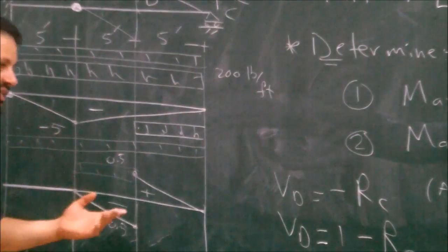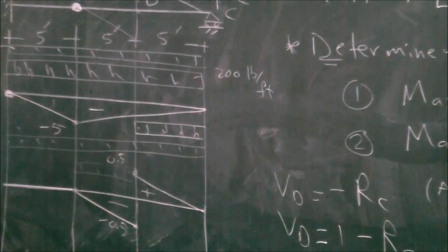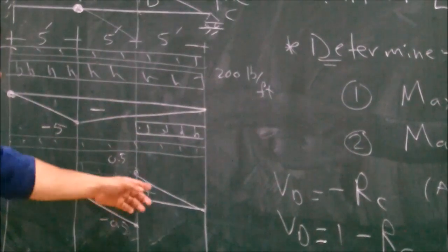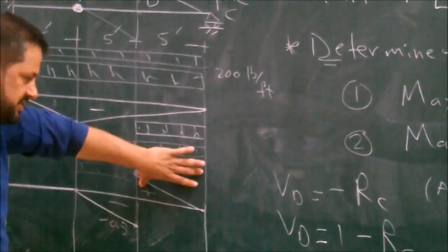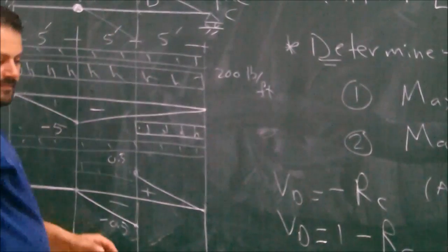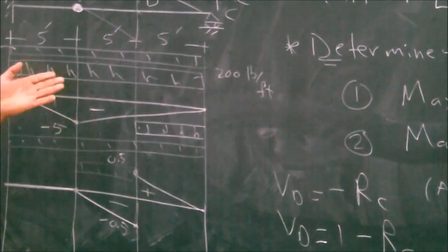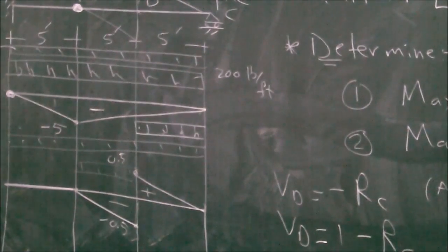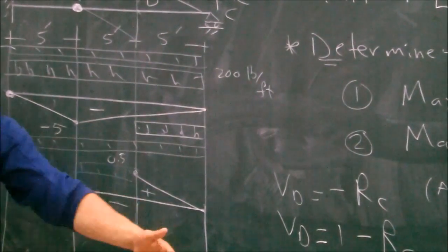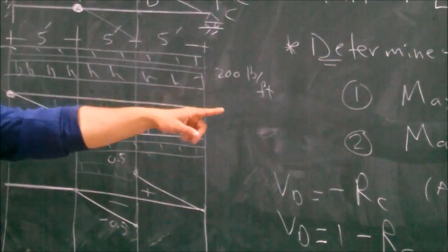You want the maximum shear developed due to this loading. You place it where you want it; if you want the positive, you place it on the positive area. This is the bridge. If you load the full bridge, you will have zero shear. If you load half of it, you will have positive shear, and you have to design for that shear.